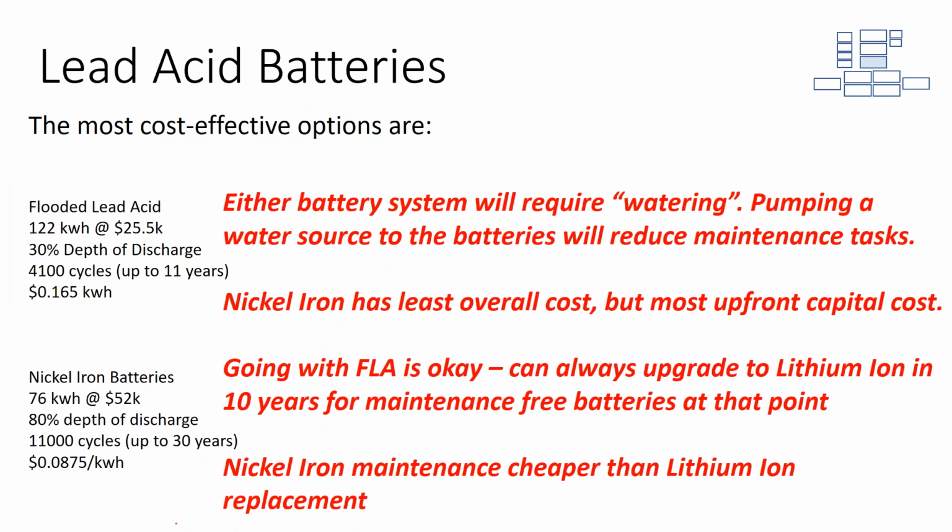And so that's something that you can consider across all aspects of projects, not just luxury off-grid residential, but if you're trying to do a small off-grid project, or even just dipping your toe into commercial load leveling, you can use lead acid for small off-grid and for commercial load leveling. It's just that the batteries will brick faster. If you use golf cart batteries instead of forklift batteries, it might be that the batteries last 4 years instead of 11 years, but they're also substantially cheaper.